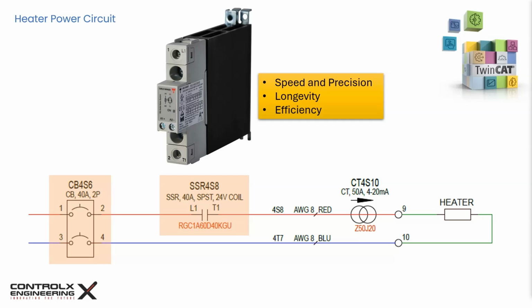They can switch on and off at high frequencies, which is crucial for effective PWM and maintaining accurate temperature control. They have a long life, since there are no moving parts and SSRs experience no degradation from mechanical wear, making them ideal for demanding industrial applications. And finally, SSRs generate less noise and electromagnetic interference compared with mechanical relays, thereby offering cleaner and highly efficient operation.